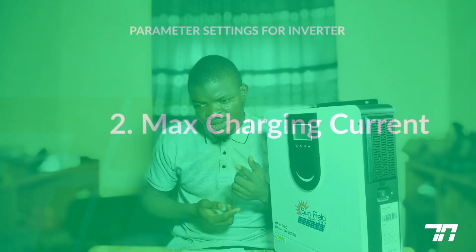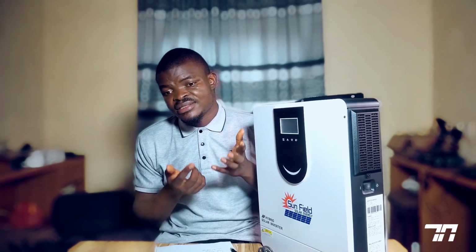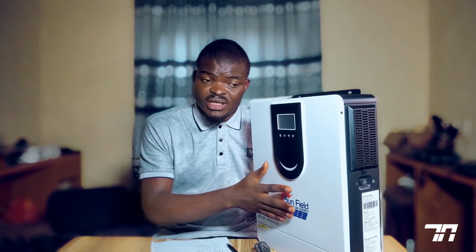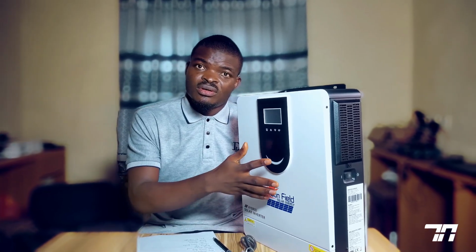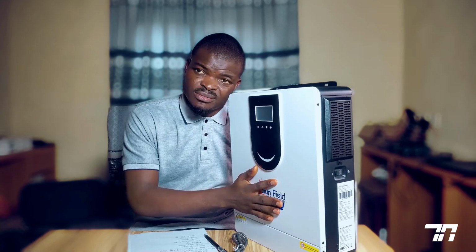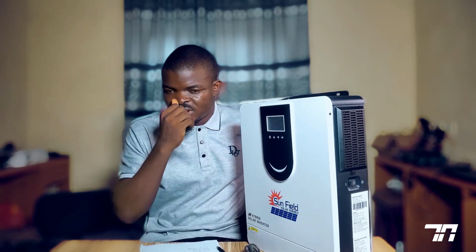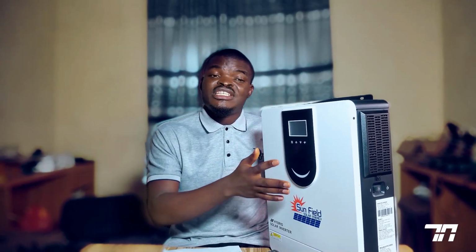The second one is maximum charging current. You need to set your maximum charging current, and the maximum charging current is the result of utility charging current and solar charging current. This one has about 140 amps maximum charging current. So utility alone can charge with 100 amps, then if you add solar to it, 40 amps, that is 140. The utility might not be charging with up to 40 amps. Maybe just set it to like 50 amps, then solar will be charging with like 60 amps, but just so that the maximum charging current is 140. That's for this particular one in front of me.